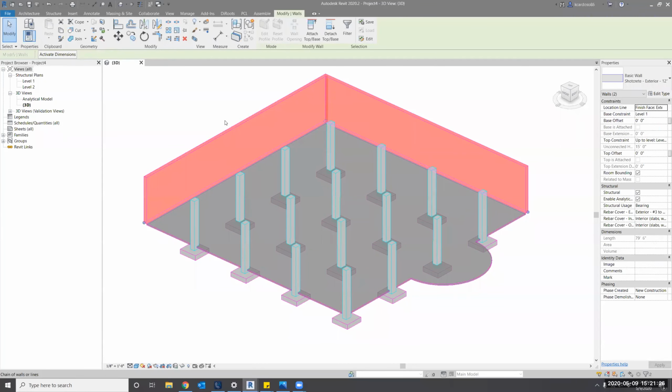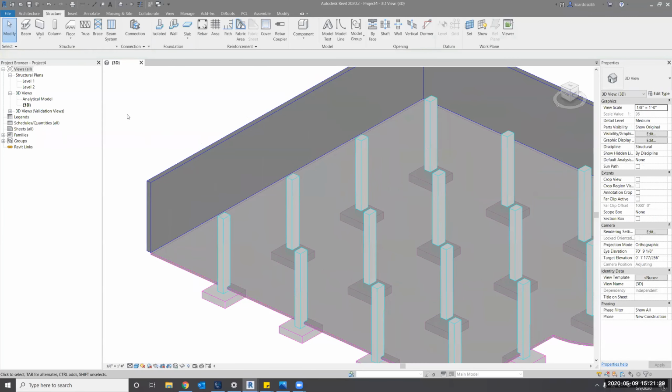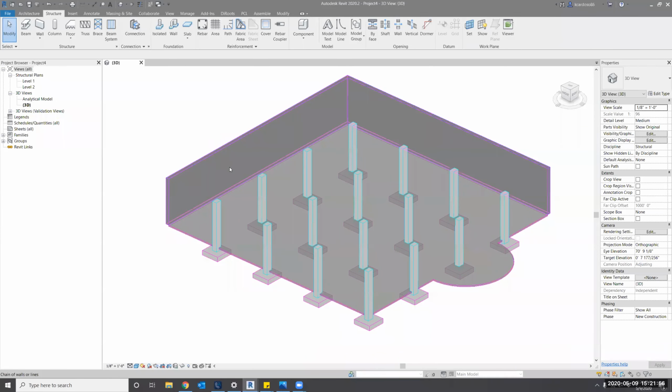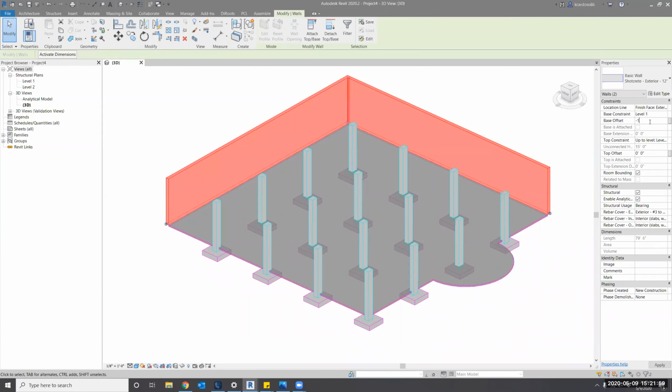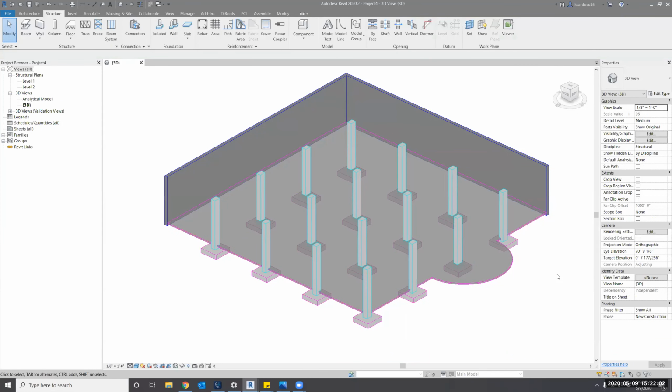Another important thing that will help some of you guys, this little drop down right there, allows you to select elements by face. Right now, if I uncheck that and come back, it doesn't allow me to select the wall. I have to hover over a corner to select it. I prefer to select elements by face. It's quicker for me personally. So just in case some of you were wondering, that's the option that I'm using right now. Okay, so there you go. So hover, tab, click in the properties, this one. All right, so far, so good.